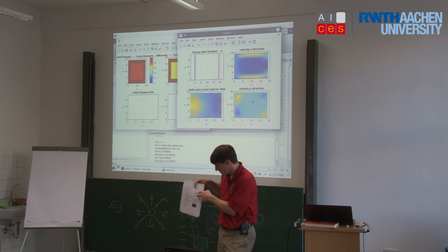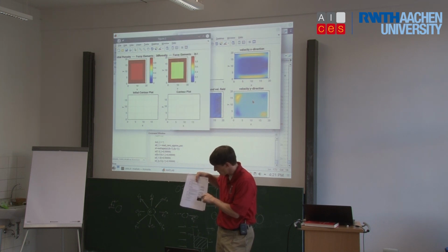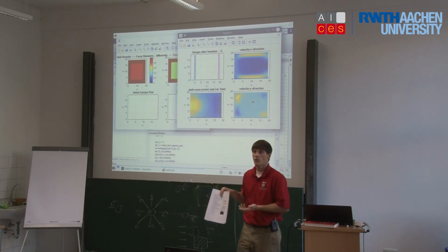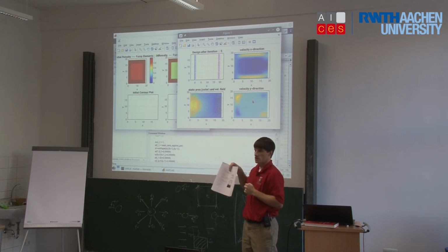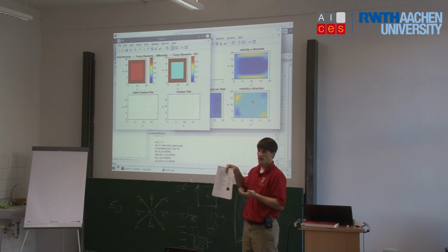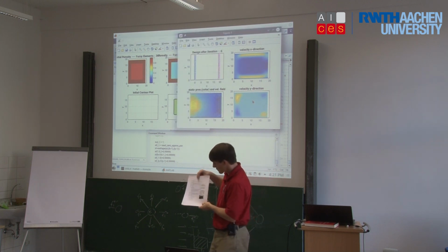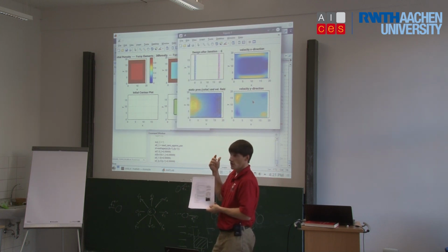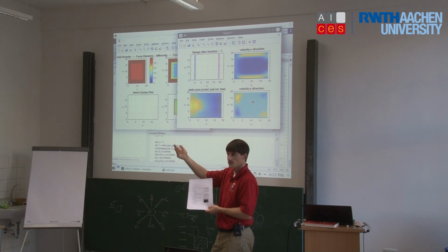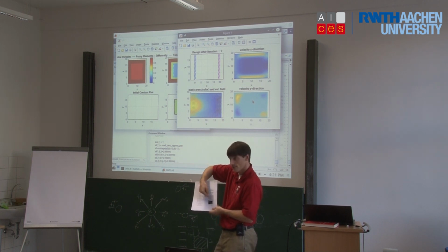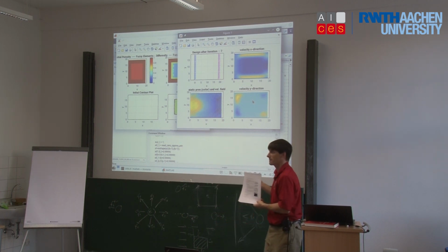And so it will optimize the shape. The next one is you have an inlet on the left-hand side, you have an outlet at the bottom side, and you now want to know what is the bent channel that will lead to the lowest amount of drag. If you look through the literature, you'll find that the lower the velocity, the more of a straight channel you get, and the more you increase the velocity, the more of a bent channel you'll get for that example problem.